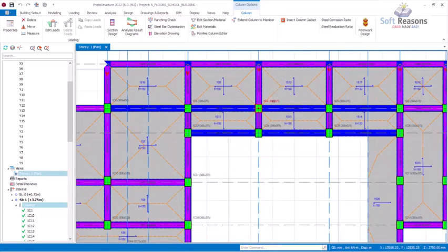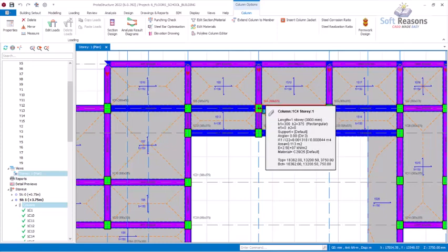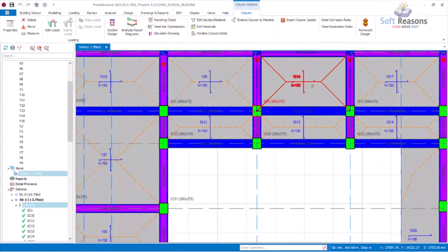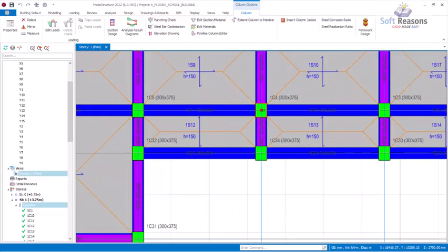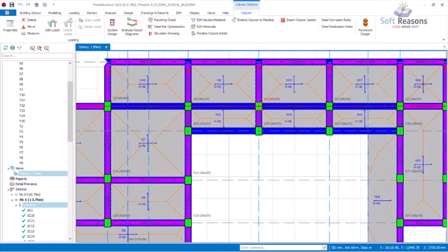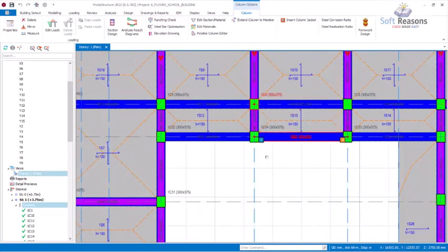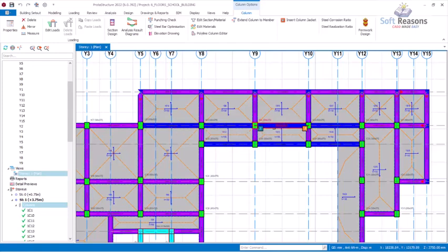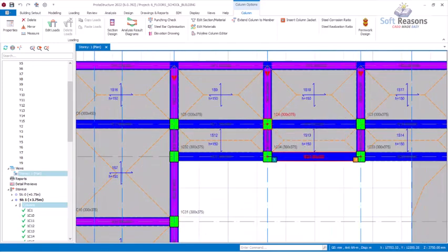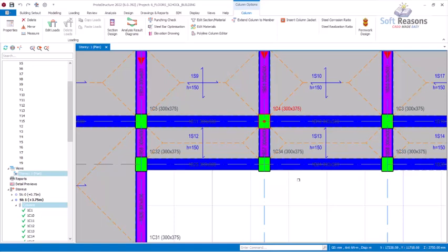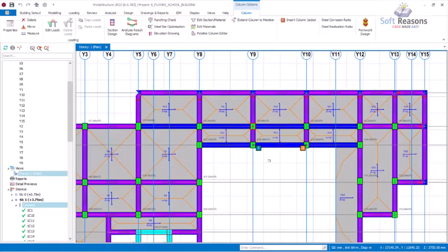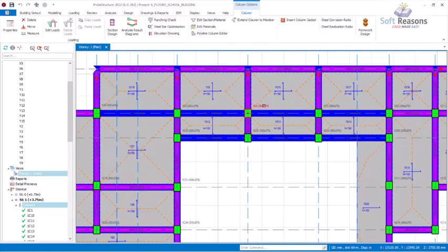Now come over to this one we have checked, and we have 6Y16. Now this one, there are no bigger panels right here. All of these panels are just smaller panels, so the load coming on this column is not that much. So this column section can as well be reduced successfully, and you will still have what you call an economical design. These are the points and the keys that you have to have at your fingertips, so in the process of carrying out your design, you apply them to have a standard design successfully. So let's get back here.